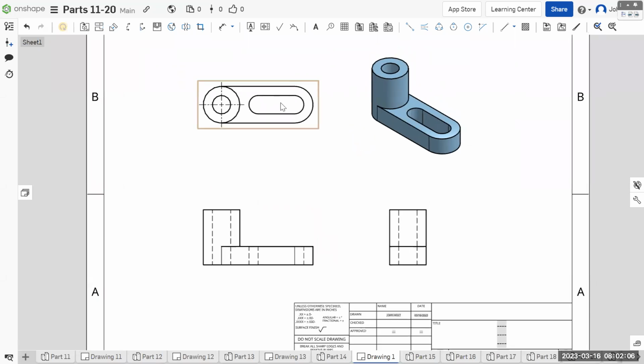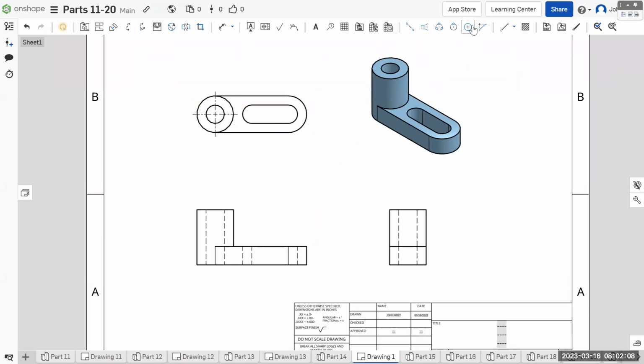Okay, curved surfaces, well, center marks. We only have 2 center marks we need to add. Nothing else looks, oh wait, and this outside one. And now what about through? The things that go through are on this 2-point or 2-edge center line between here and here, which I don't know why it won't let me select both those at the same time, but there you go.